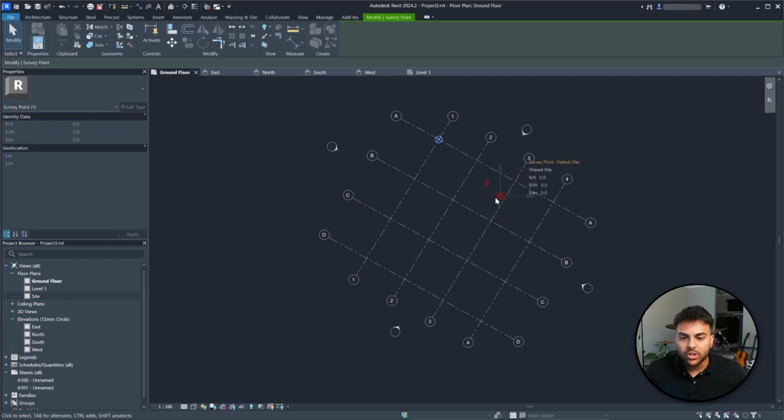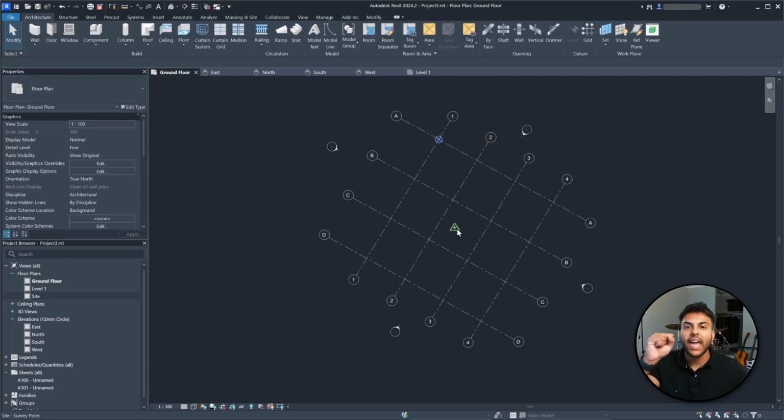So one more thing which I did want to say, you can move this around, and this is where your 0, 0, 0 is located, and this will change with respect to your survey point, right? So the values which I had here are different. So that's 5609 to the values which I have down here, because you're just relocating the origin, right? Imagine a Cartesian plane, an axis. If you relocate the origin, you relocate the coordinates, even though the coordinates might stay the same, right?